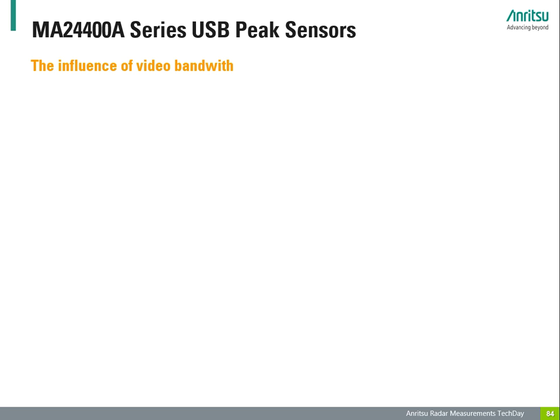This will manifest itself as measurement errors and can be in either direction depending upon the signal and detector characteristics. The rate at which a detector can follow the envelope can be described by rating the sensor's rise time with a pulse signal or its small signal bandwidth with an AM signal.